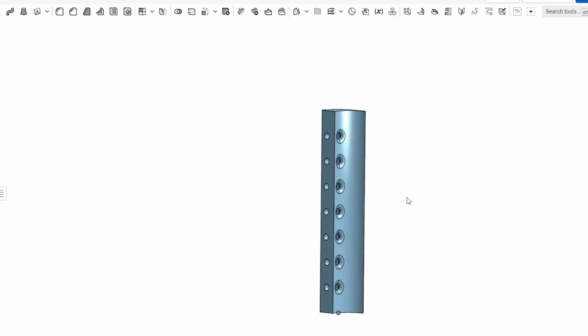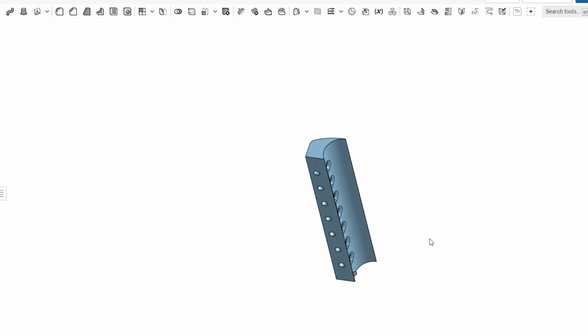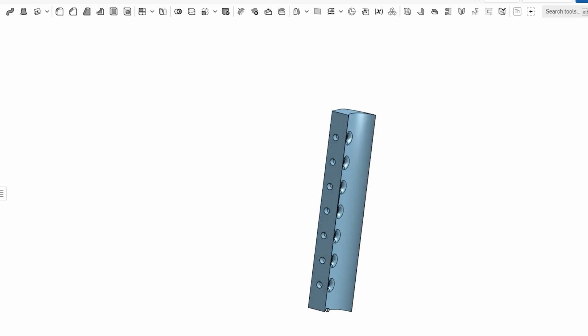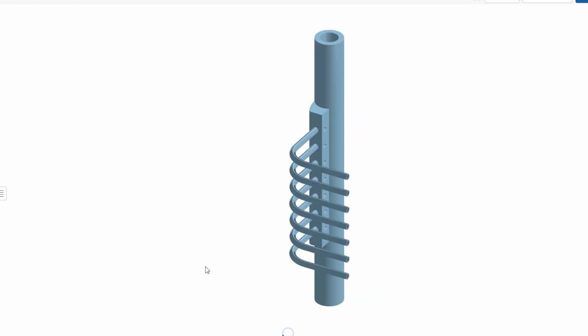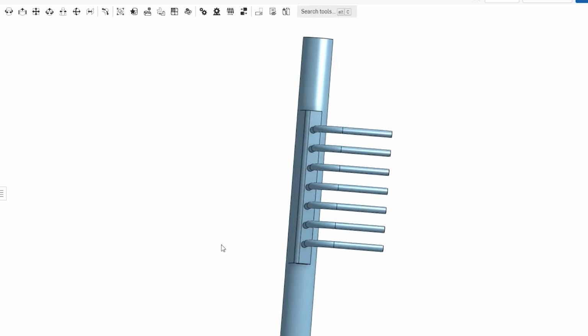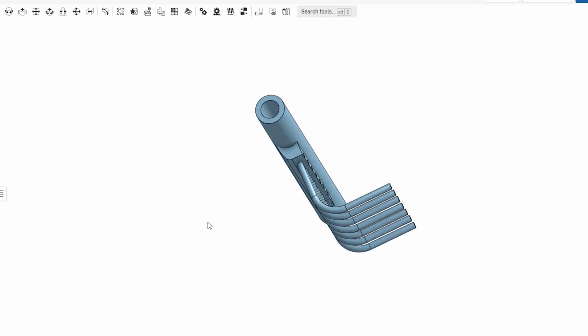Okay. After a few more failures and a lot more research, I came up with this next design. Spoiler: this one worked. This design consists of a 3/4 inch PVC pipe manifold, a 3D printed attachment, and several pieces of 1/4 inch copper tubing. This gives me much more volume, and the long, smooth pieces of copper tubing help to maintain the laminar flow of the smoke.